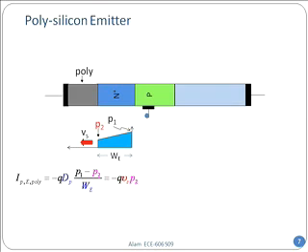Can I solve for P2 now? I think I can. That's the ratio, P2 divided by P1, and that's related to the diffusion coefficient and the surface recombination velocity. Do you agree with this statement? Does it look right? If the surface recombination velocity was very large, like metal, then in that expression, Vs should have been infinity, right? Let's say, relatively speaking. If that's the case, what would have been the value for P2? That would have been 0. That says that indeed, if it's a metal, then P2 must be 0.